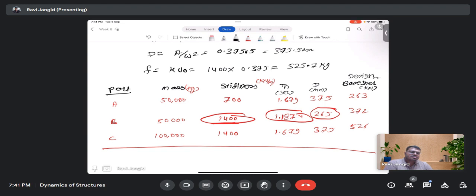No, no, no. You have to understand that what happens is when you define the stiffness of the column member or water tank, let us say a single column, the more you make it rigid, the more forces it will attract. So you have to make it a little bit flexible. Then the forces, base shear, will be less actually. The more you make it rigid, the more seismic forces it will attract.